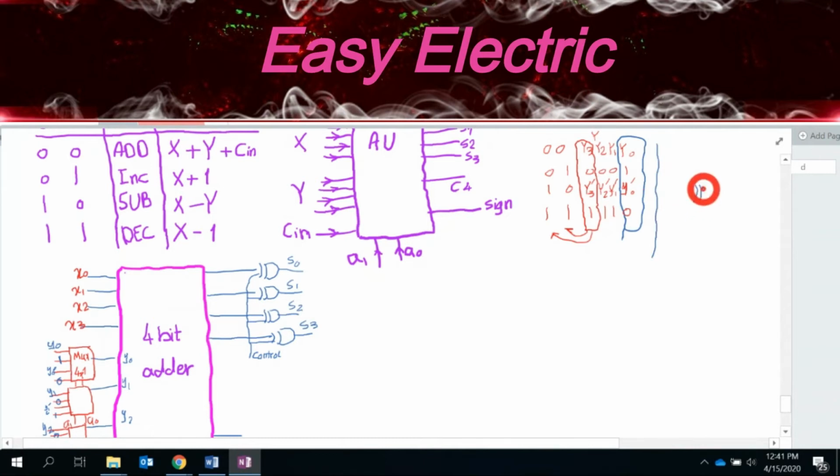Remember, I talked about the switch XOR. I put one input X, I put another one C. Then you have this output, which we call F, right? Definitely F is x c prime plus c x prime based off the definition of the XOR. So based off that, if I give c equals 0 and c equals 1, whenever c is 0, what should be the F? Type in the chat box. If c is 0, what should be F?